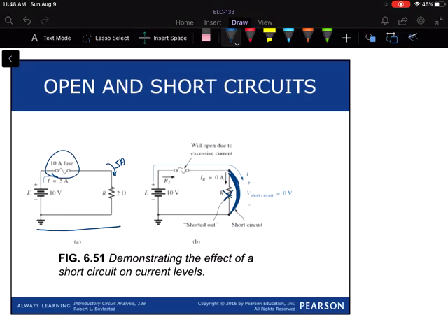We say that our resistor is shorted out because current now has a path to take around the resistor to get to where it's going. So what happens here is now we have nothing to limit the current, and it gets very, very high in the circuit, the current goes above the 10 amps, and then the fuse opens.